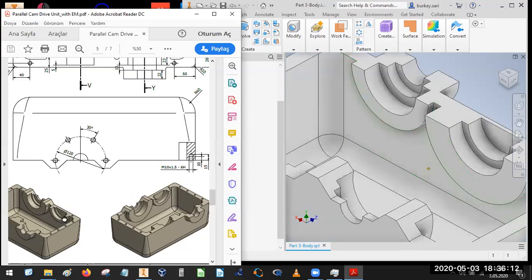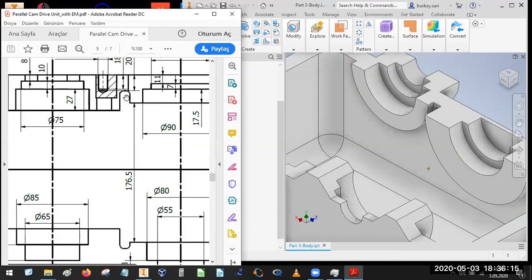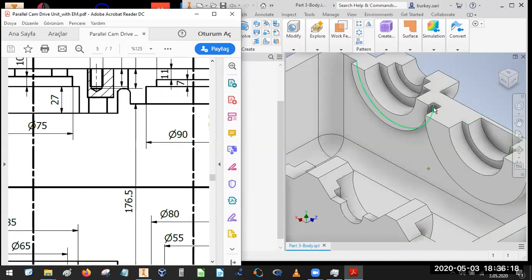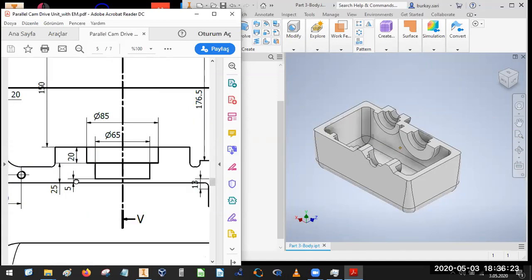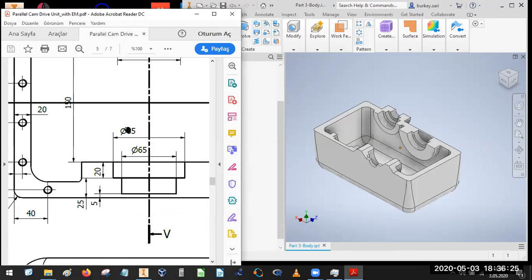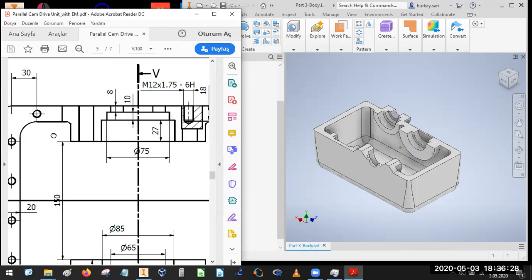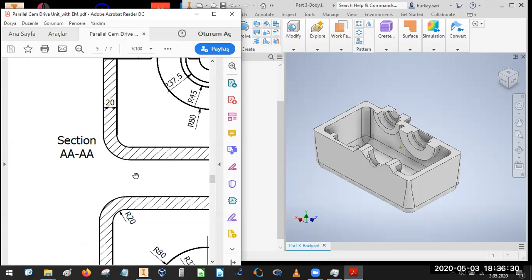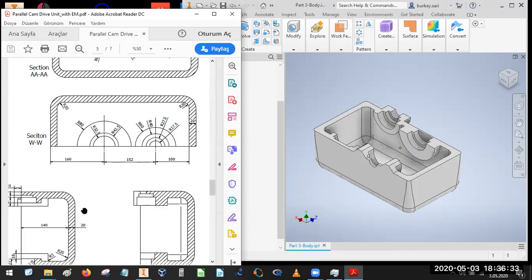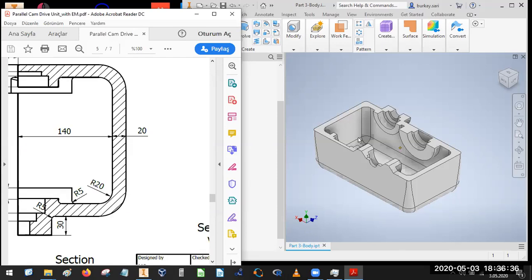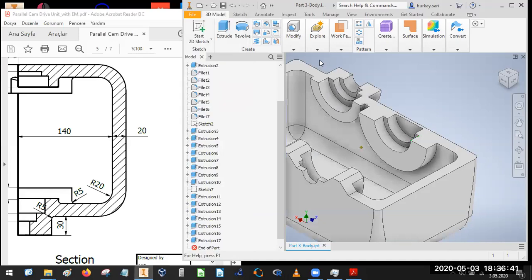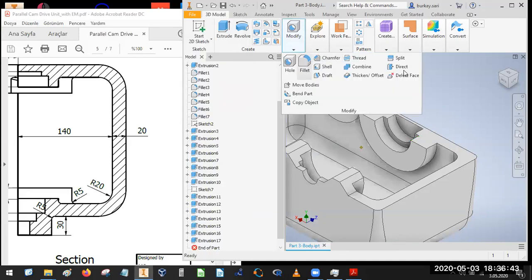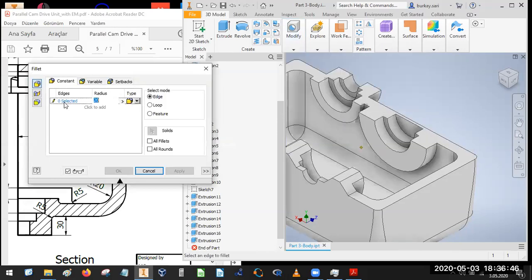Also, some fillets, which are here, the back sides. You can just make it as you wish. We have the fillets, as you see here, the rounds. Let me look for those dimensions I have made. Yes, the 5mm fillets on each side here. These fillets reduce the stress concentrations.